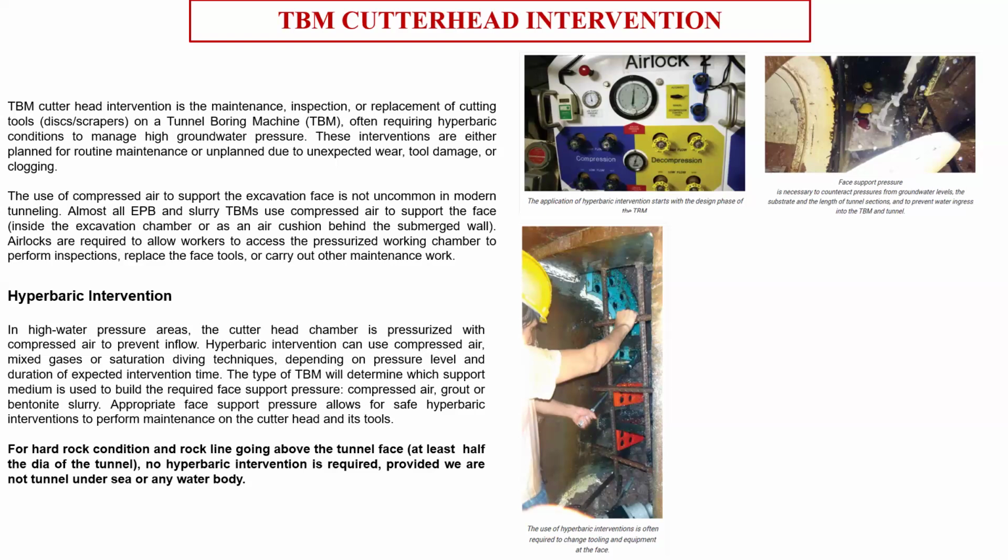Because I have designed my segment, I have given my segment tolerance, the circle tolerance. Now the TBM itself has a tolerance, and inside the curve it also has a tolerance in the alignment. So everything has been decided. Now once the segments have been installed and the operation has been done, I get the survey data. Ring by ring, as per the alignment, I will check whether the circle is perfectly fitting.